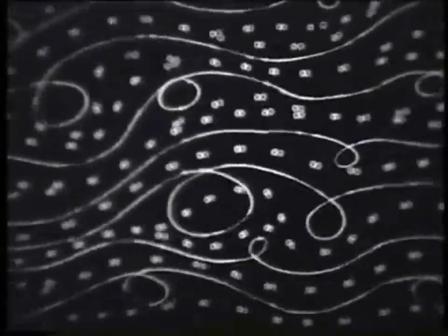Consider the dynamics of the flow in the inter-electrode gap. When the flow enters a narrow gap, the pressure drops. The action of molecular forces forms a layer of stationary molecules 3 to 7 microns thick at the surface of the electrodes. The neighboring layer is moving at a low speed. In the layers further away from the electrode, the flow rate increases. Here, at a certain flow velocity, a turbulent regime is established, which ensures the best removal of dissolution products. The process does not stop even at high current densities.